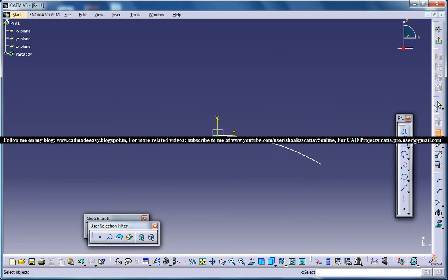Okay, and you could select the arrow and pull out this point and just imagine in your mind how the curvature of the umbrella would look from the side view. So something like this makes sense for me. You could put it here, and if you want, you can put a radius for this, so it gets constrained. Right, now come out of the sketch.